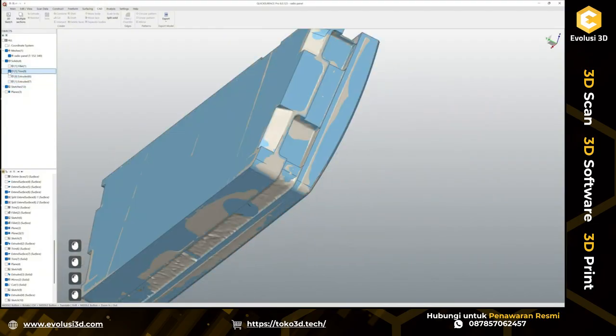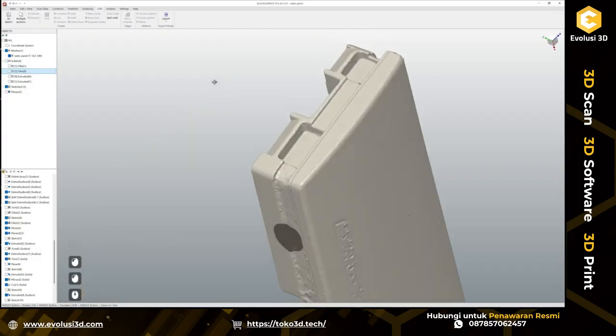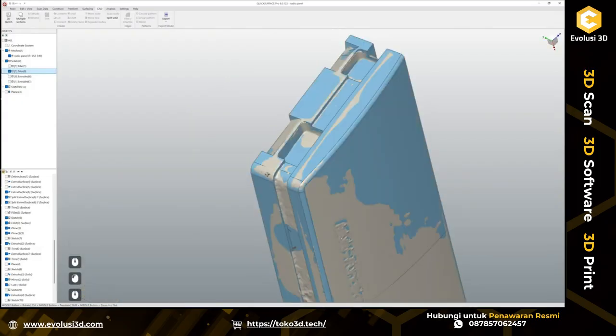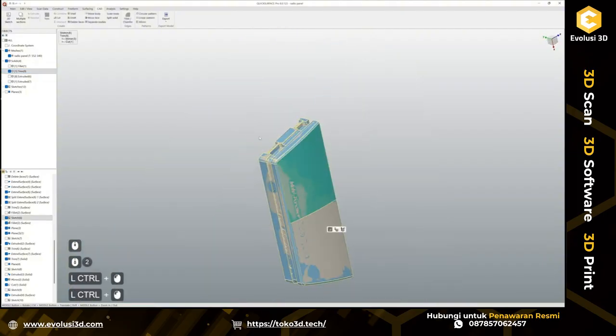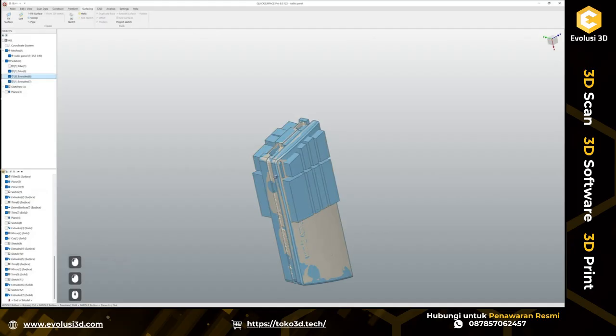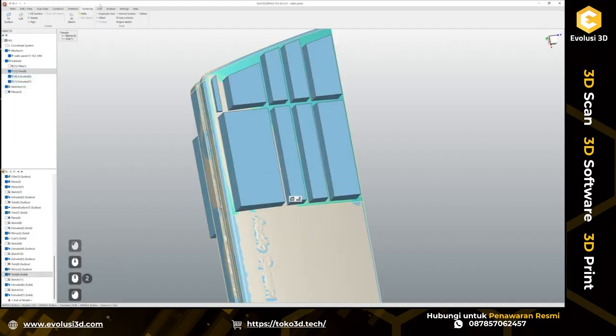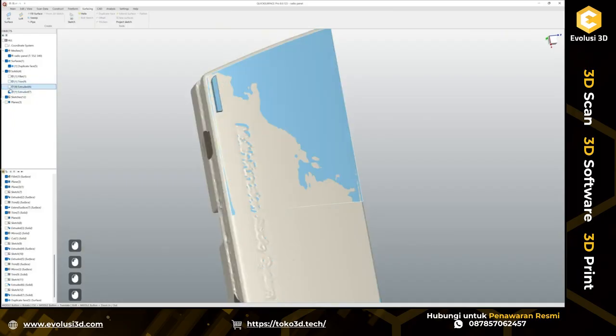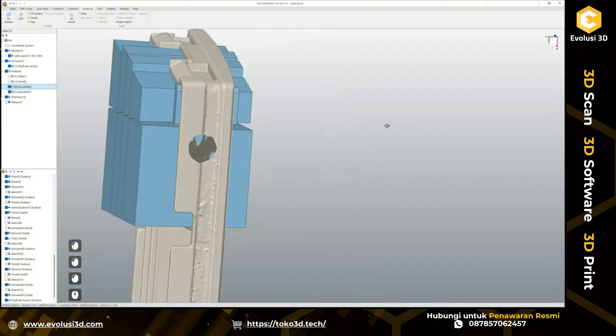Now I simply need to trim them to make a cutting tool, and in order to do that, I'm going to duplicate this surface again. Oops, not one of them. I need both sides. Or actually, just one side will work good enough. So let's hide all of that.